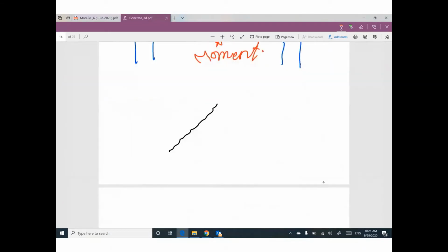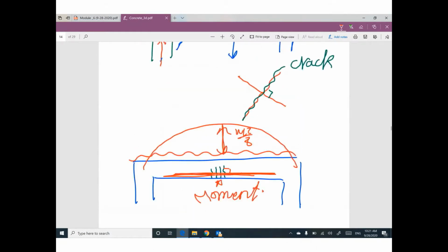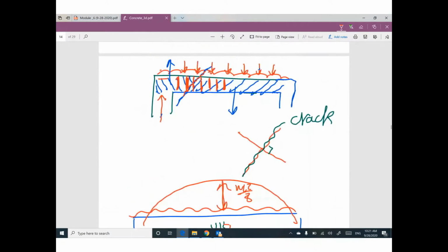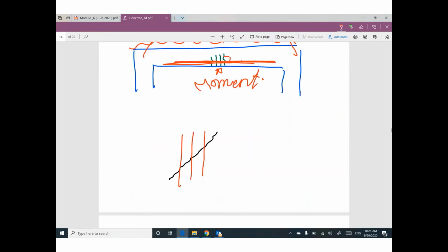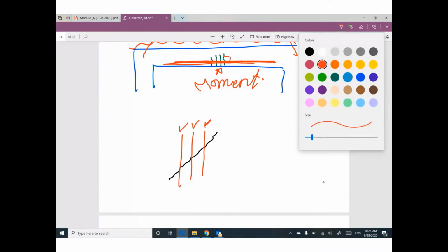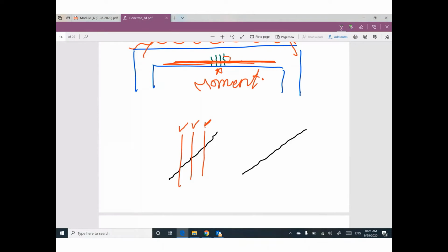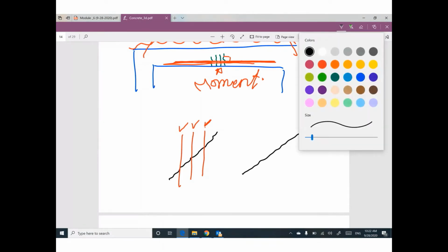Like this. And you just told us it's recommended to make reinforcement perpendicular to the crack. That's right. So do you think these stirrups will be efficient? Probably not. If you have cracks like this, the most efficient stirrups must look like this.